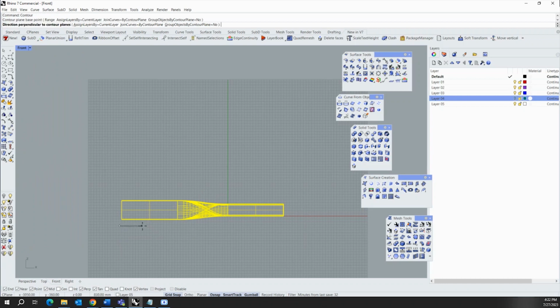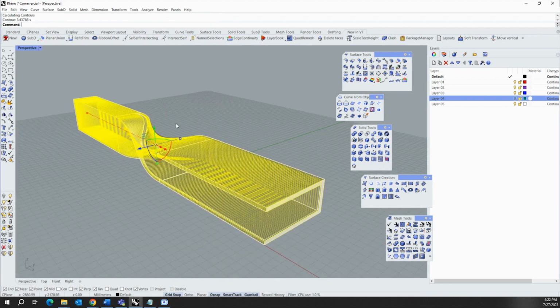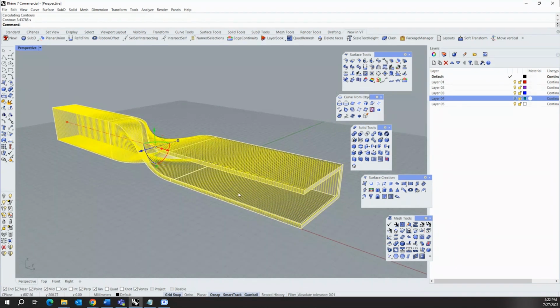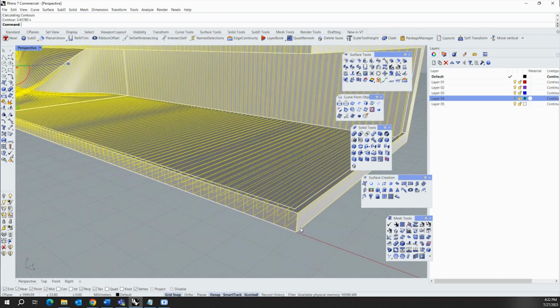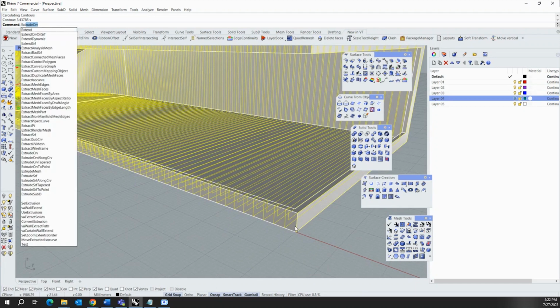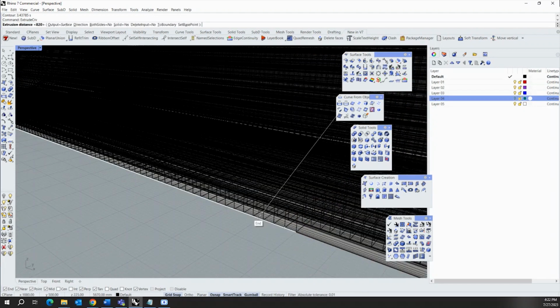and just make the line and enter. So it will give me this series of lines when I do contour. I'll take that as a reference. It's like a section, like an intersection of this overall form cut through each 30 mm distance. So I'll be taking this reference, and I'll be creating a solid form out of this. I'll do extrude curve.